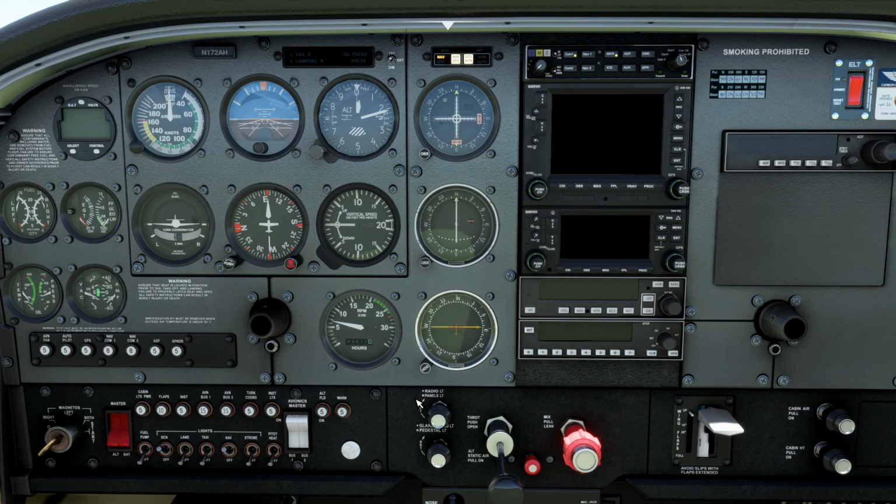So let's talk about powering up the autopilot and pre-flight of the autopilot. The autopilot is powered from the bus 1 side of the avionics master switch. It will also power up automatically anytime you drop into Flight Simulator in other than a cold and dark state. And the only time you're going to get a cold and dark state is if you start your simulator session on the ramp.